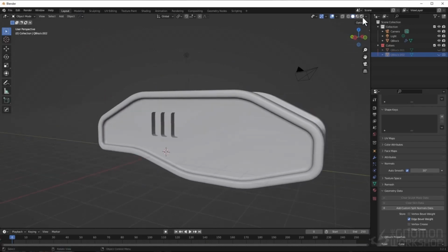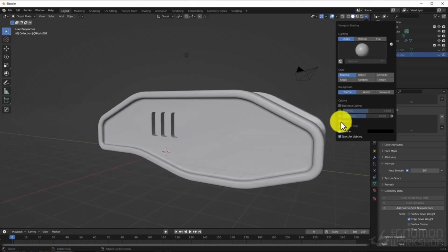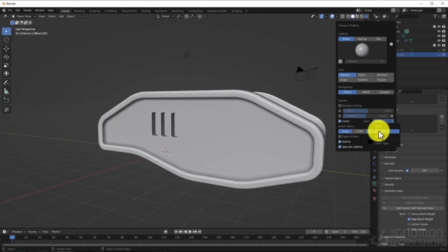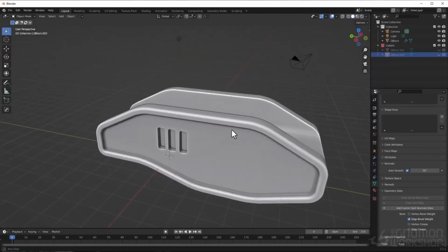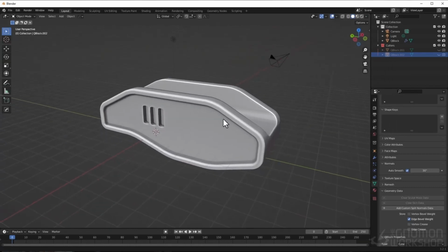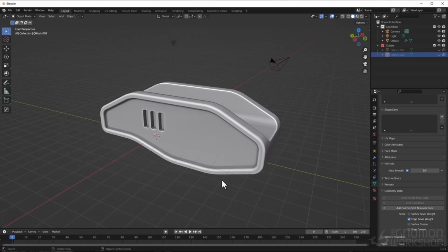When I'm modelling, I also like to turn on cavity in the viewport shading options so I can see my shapes a bit better. I'll now show the modelling process sped up, but for the most part, I'll only be using these basic techniques. The only other important technique I use is to create tube and frame shapes, but I'll point that out when we get to it.